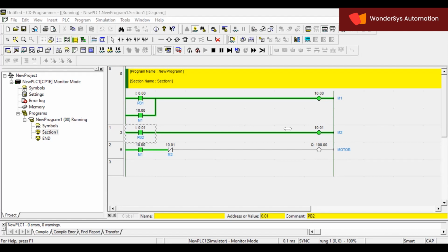Now, we'll tell that, right? Whenever we are writing the PLC program, the input address cannot be repeated at the output side. Here we can repeat them. The same address will hold it. And the output address can be repeated at the input side. Okay, understood?